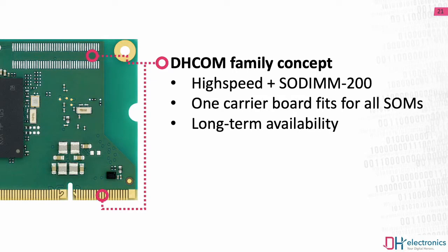The first components I'd like to highlight on the DHCOM module is of course its SODIMM connector and its high-speed connector. These two connectors are standardized throughout all of our DHCOM system modules, and therefore once you've designed a carrier board, your baseboard will not just fit this specific DHCOM module, but instead it is compatible to the whole DHCOM ecosystem. And this gives you a few advantages.